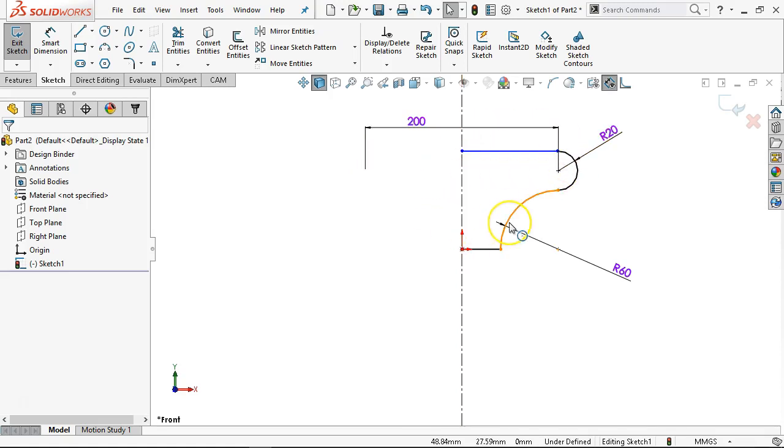If this becomes a revolve, then it's already at its diameter. All right, so let's make this a revolve real quick just for fun. We're going to do so many boss extrudes that we don't get to do too much in the way of revolves until later. So the way I differentiate is that if you're familiar with the manufacturing processes, if you're putting this part on a mill and you're going to machine it prismatically, or you're going to put this on a lathe and machine it cylindrically, then that's going to drive